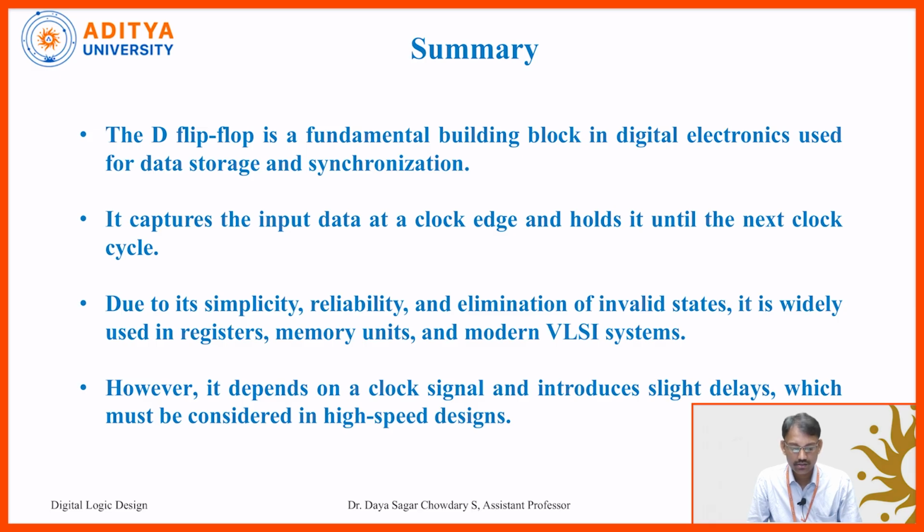And coming to the summary, the D flip-flop is a fundamental building block in digital electronics used for data storage and synchronization. It captures the input data at a clock edge and holds it until the next clock cycle. Due to its simplicity, reliability and elimination of invalid states, it is widely used in registers, memory units and modern VLSI systems. However, it depends on a clock signal and introduces slight delays which must be considered in high-speed designs.